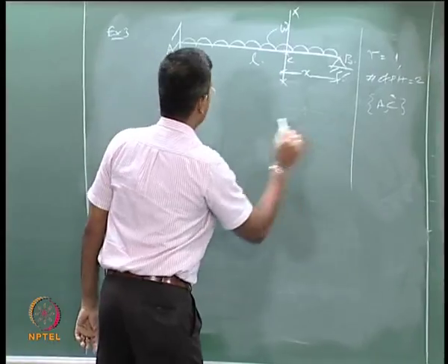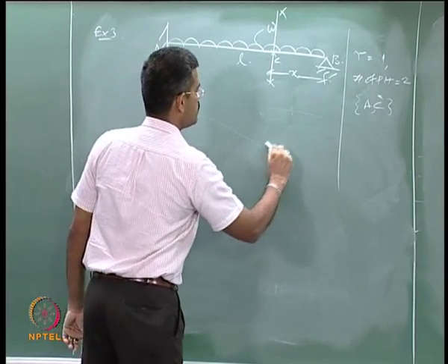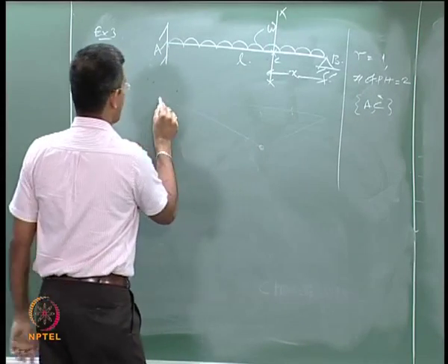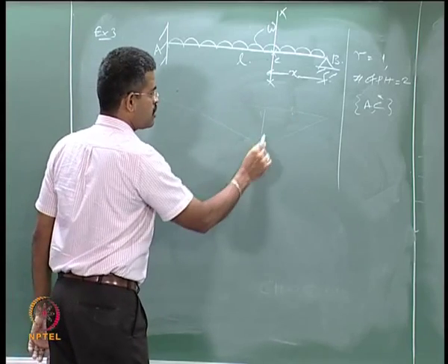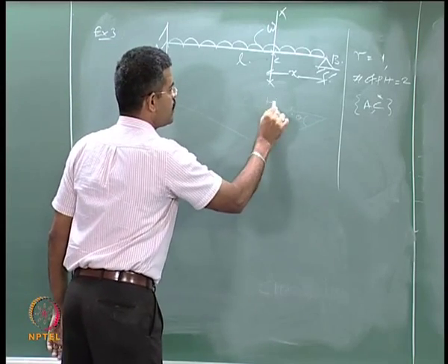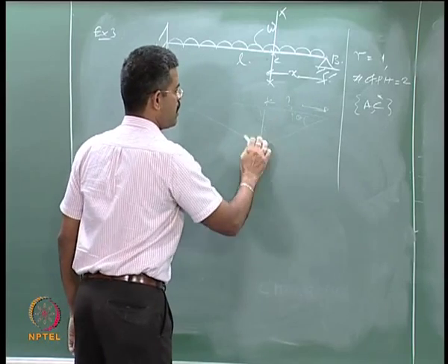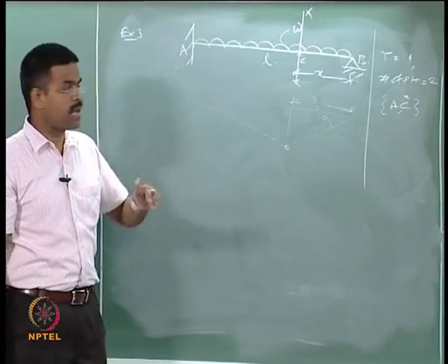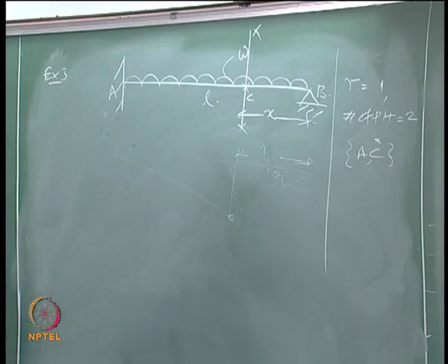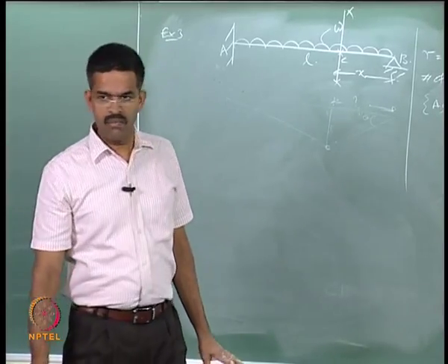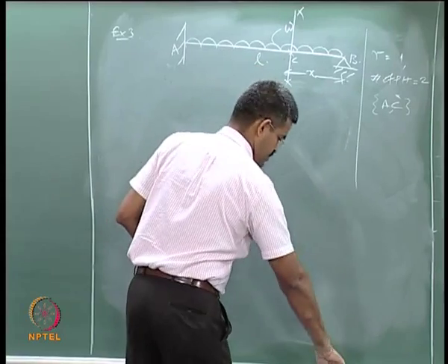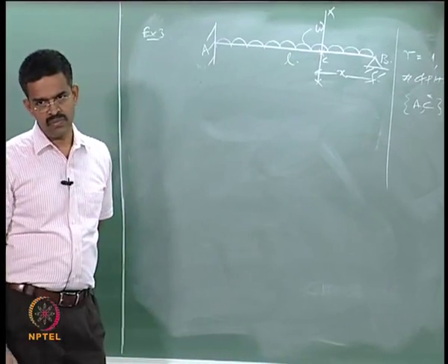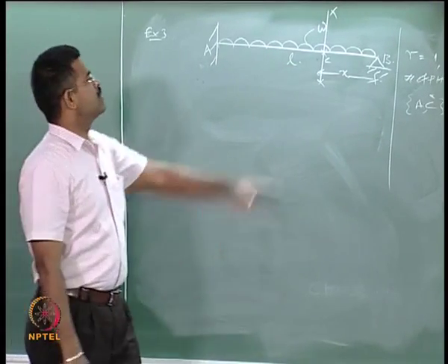Okay. So if I directly apply the kinematic theorem to this, the kinematic theorem says draw a hinge location and form a hinge here, form a hinge here, external virtual work, internal. So I should know delta, I know theta. Now if I do not know this, I cannot find delta and theta, is it not? So I cannot apply the kinematic theorem to this. Okay. Can I apply the static theorem to this? I do not know what is the bending moment at this point, is it not?